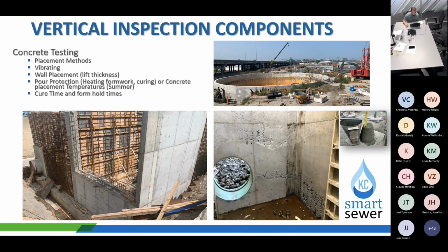So, I definitely say take a few minutes when you get on these projects, if you're going to be responsible for checking concrete, to read through the Division 3 specs, specifically the 3300s, where a lot of the meat and potatoes are on this. But read through all of them because things may vary from project to project. Understanding what the contract says in relation to how the concrete's going to be placed, whether or not the contractor's allowed to use specific types of formwork, understanding the pouring rates, how concrete's going to actually be placed in the walls.